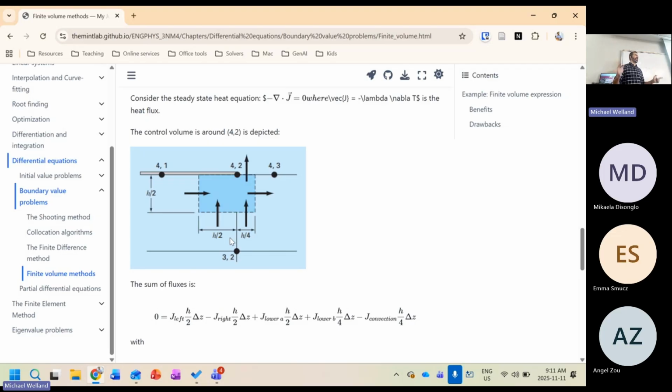It's gonna find the same solution. Here's the magic part. It's gonna find the same solution because the solution to your equation doesn't depend on whether you're using finite difference, finite element, or finite volume. It can't. Absolutely can't. So at the end of the day, your heat flux and your solution are going to look something like that, right?